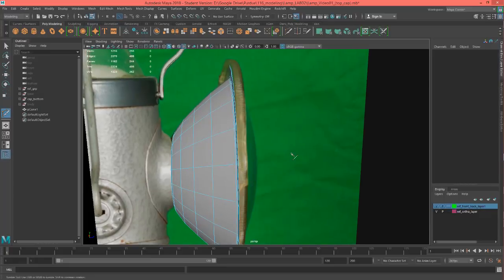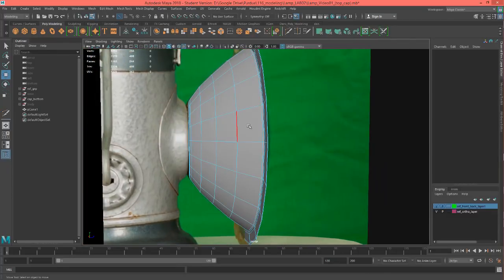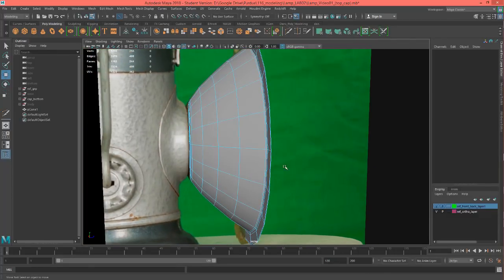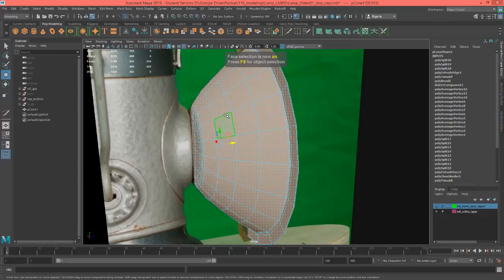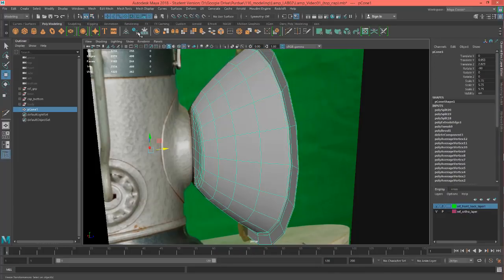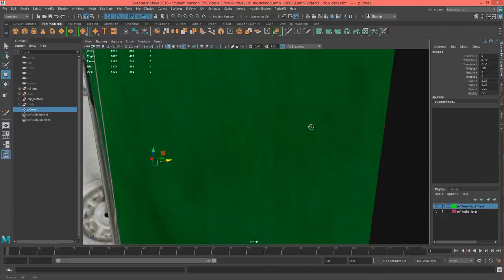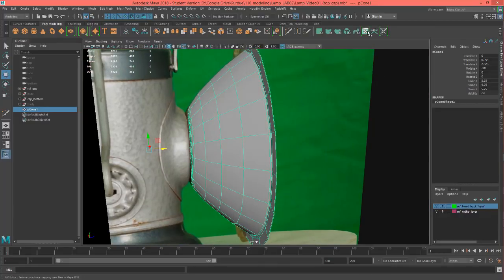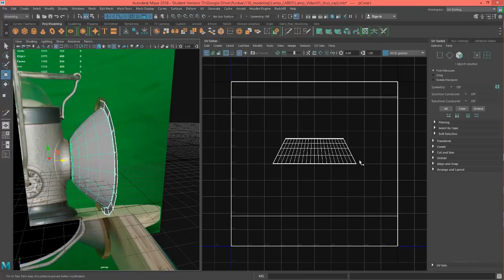And now what we're going to do is that thicken trick again that we did over here. So we're just going to basically take the geo that we have and thicken it. But remember how we did our UVs. So let's go ahead and get the UVs out of the way. And before I do that, I always like to delete the history when I see a really long list, just because Maya starts to slow down a little bit. So I'm going to go to my UV editing.